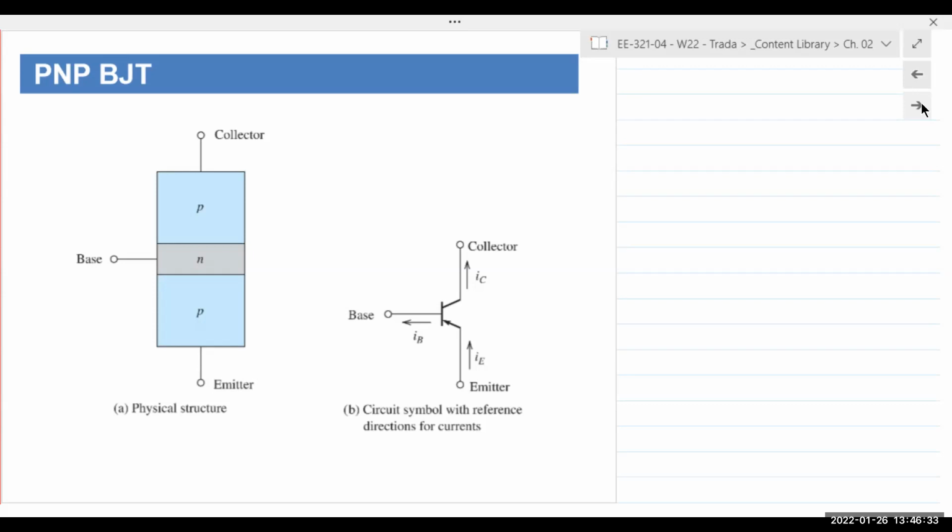You have a very thin layer of the base, but your starting material is now P or P plus. So the silicon material is P plus with a lightly doped column 5 compound. You create the opening in there and deposit your impurities to create an N-type material.